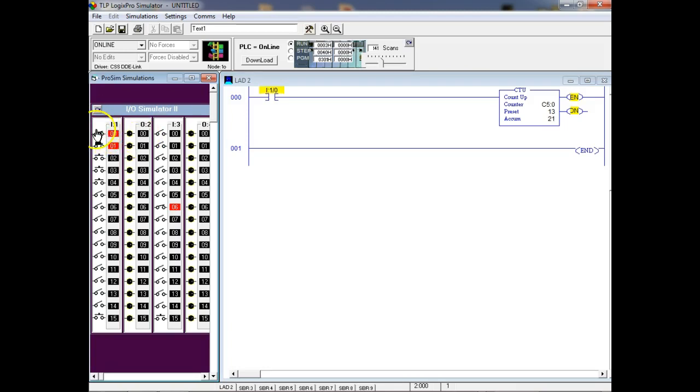So what it does is it only changes at a transition. So here it changes, and some of your PLCs give you the ability to set the transition. By default, this is when it goes from a low to a high. So only on that edge does the counter count. Okay, understand it. And that's usually true on a lot of your digital counters. We call them edge trigger.